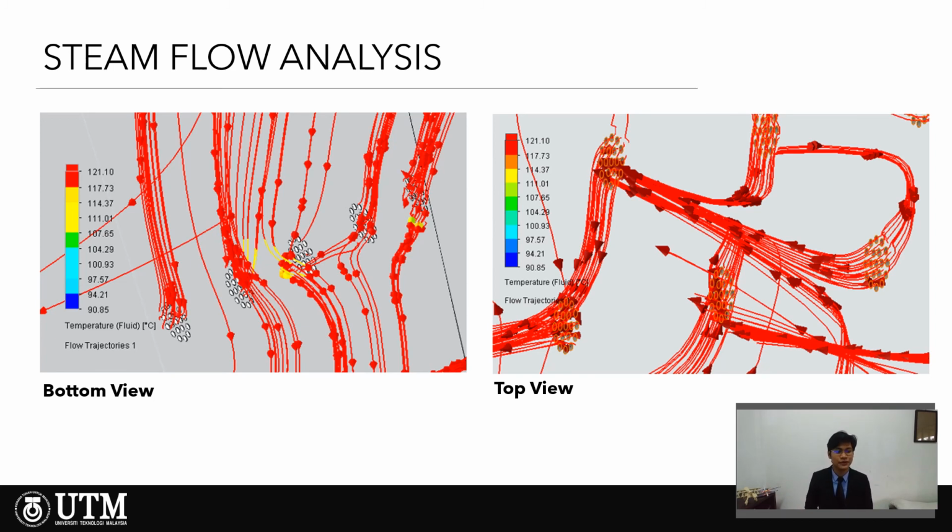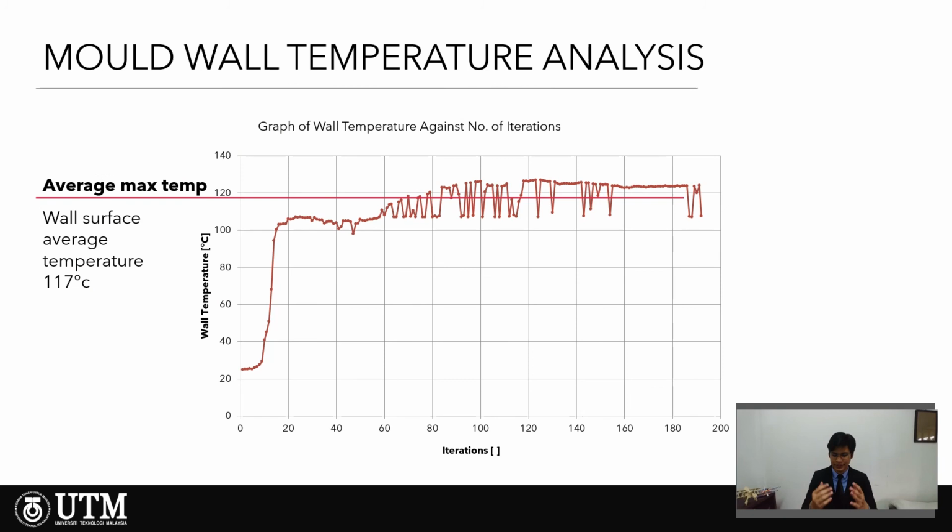Okay, as mentioned before, the mold wall heats up to 170 degrees Celsius on average. However, you can see here in the beginning that it doesn't reach that temperature first. This is because it has a high specific heat capacity, which is good because we don't want to overburn the EPS beads, causing shrinkage.